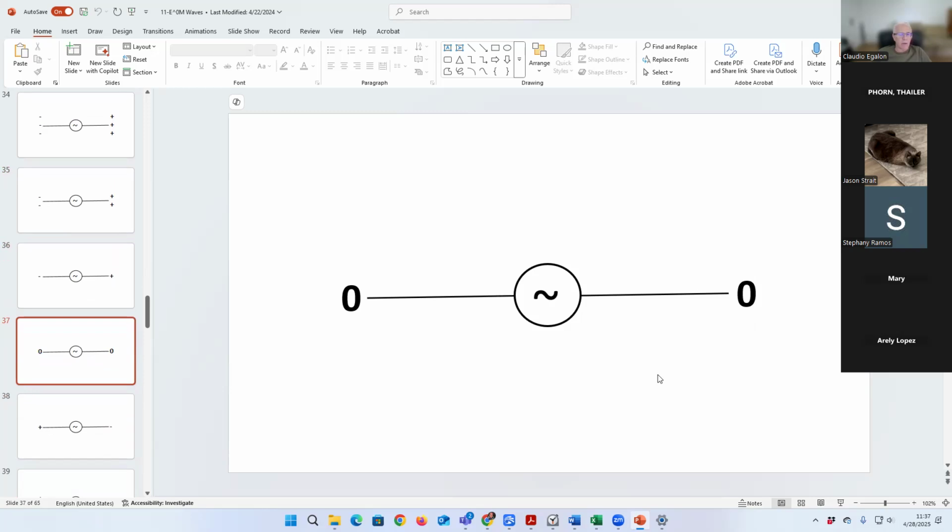Then the direction of the charge is going to change. Remember, we initially had a negative charge here on the left side, but now that we are going through the other side of the sine wave, we are going to have a positive charge build up in the left side of the antenna. Okay? Here you go. More charge, and then the cycle is closed and repeats itself. Do you picture that?